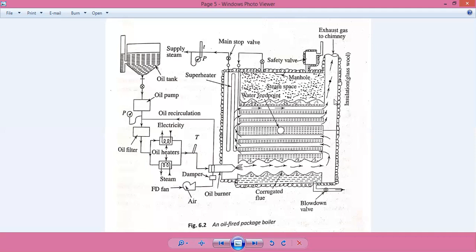There are two types: one is coal fired and one is oil fired. Just a minute, I have explained the oil fired furnace. Here, the advantage is that this is much less polluting than the coal itself. It creates much less fumes and almost no ashes at all in comparison to the coal. But the problem is, in comparison to coal, it is much costlier. Another advantage is that oil can be moved from the source to the point of use rather easily than the coal itself. Only a few drums or tankers are enough to run on oil per day.